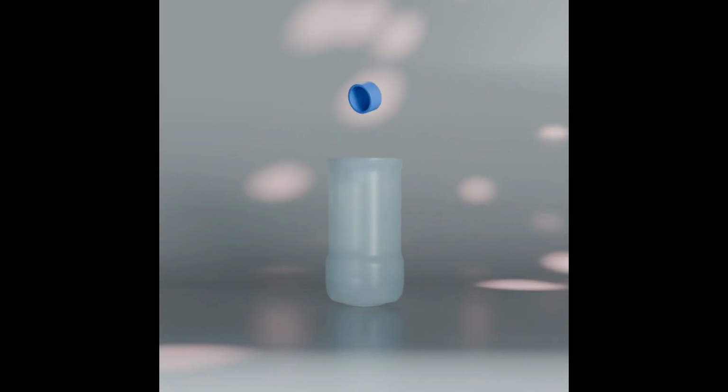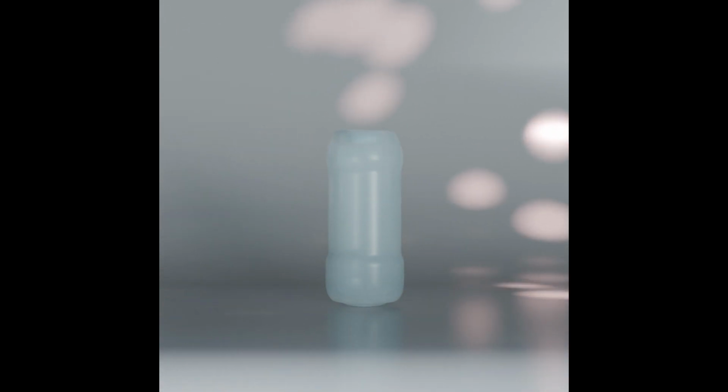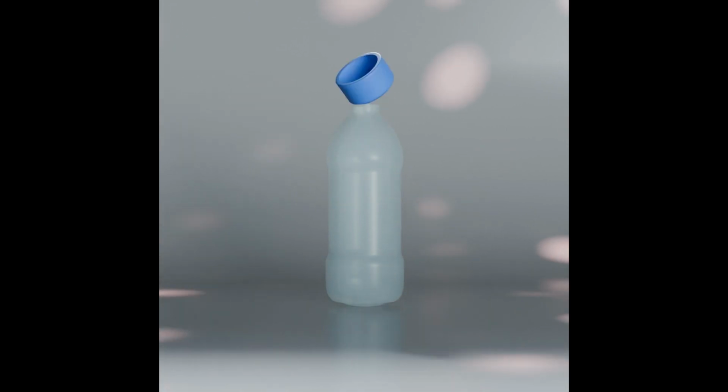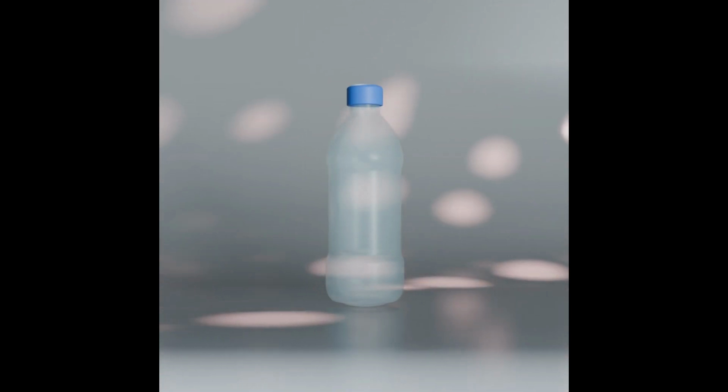In this tutorial, I'll show you how to do an animation morph between any mesh of your choice. We'll be using Blender geometry nodes to do this, but in this lesson, I'll be doing the morph between a plastic can and a soda can. This method is great for procedural modeling, allowing for easy adjustments and clean topology. Let's dive right in.